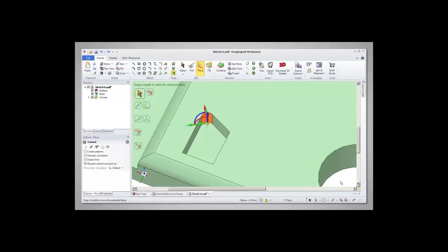It's very important to make sure the move anchor is pointing the right way before carrying out the move. The anchor will set its direction perpendicular to the surface it is sitting on. Usually, this will be straightforward and in line with the geometry of the shape. With irregular shapes, like the rounded corner of the depression for example, any move made will not be parallel to the sides of the shape, but at 90 degrees to the point on the round.